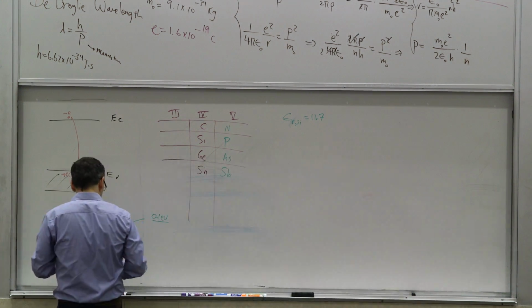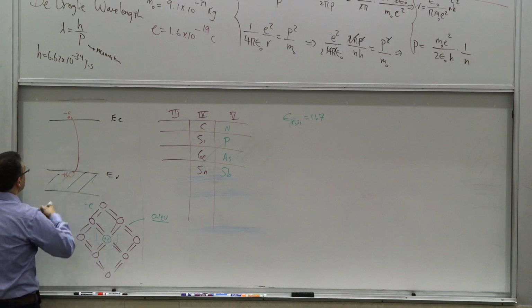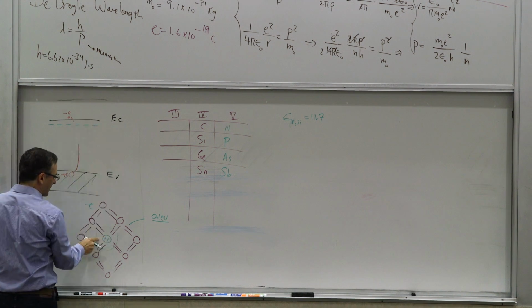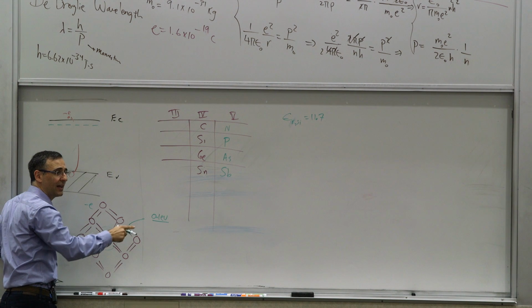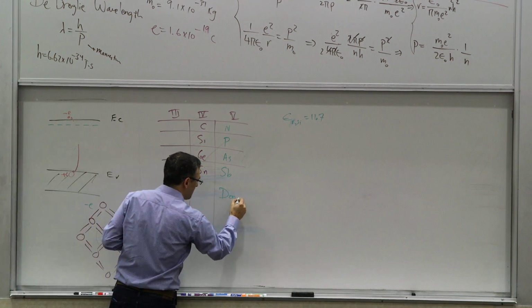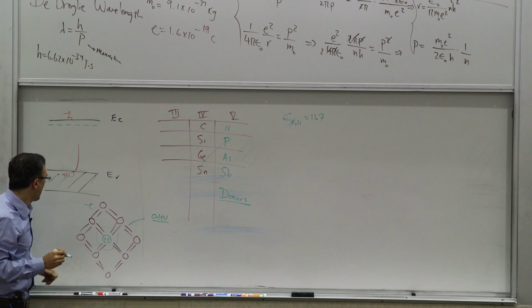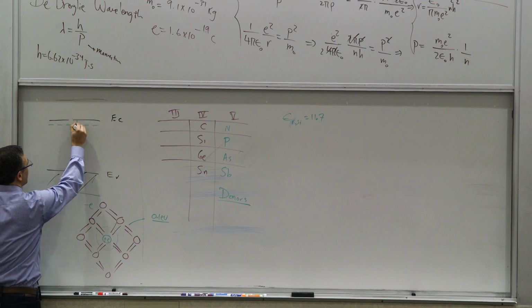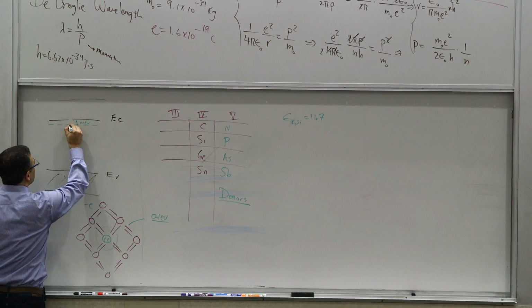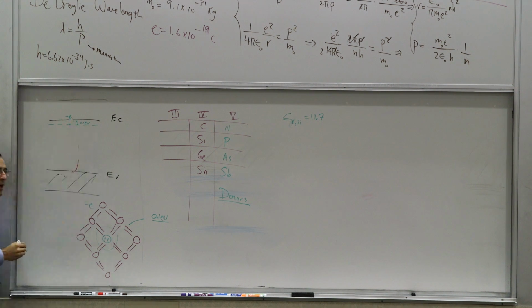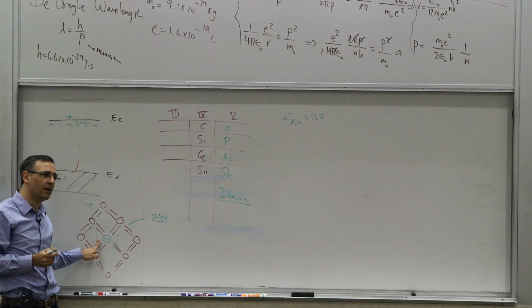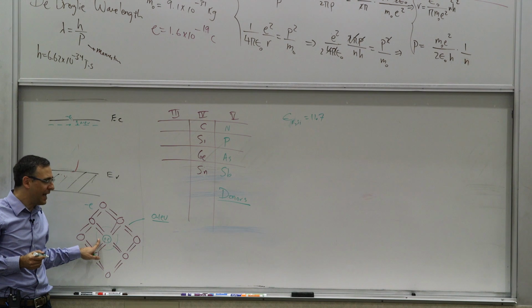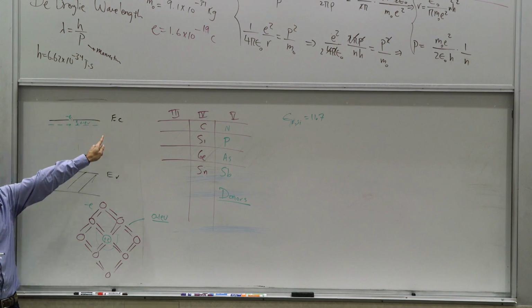So the way it looks in the energy band diagram is different though. Now you have these energy levels associated with these dopants. These are called, by the way, donors. The column 5 elements would be called donors, because obviously they donate electrons. And now you have these energy levels that are here, very close. This is like 0.1 eV. An electron can jump from here and form a free electron. And what would be left behind? A positive ion, right? Now, this electron obviously can move around. This is a free electron.